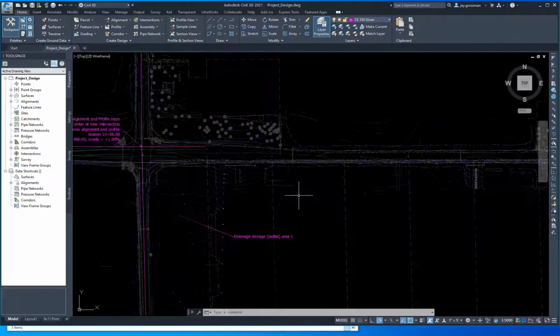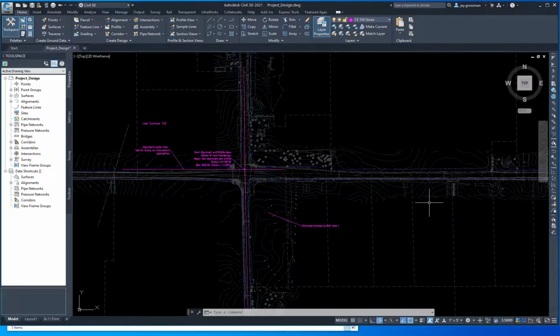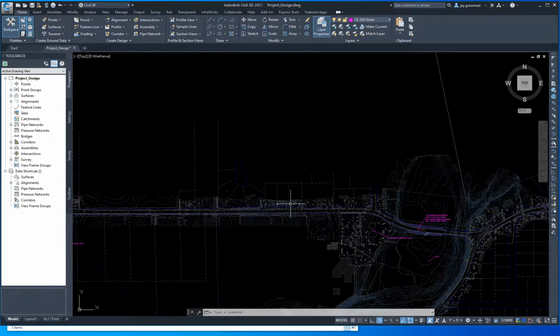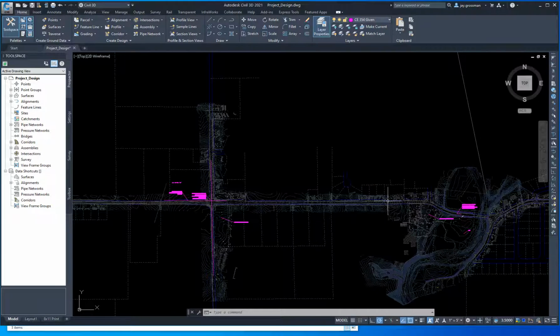You're going to look at your contours. These are your contour elevations for the natural ground level. And you're going to decide if I'm going to move the water down this direction through my ditches and then have a culvert pipe and cross over here and put my water in this area, or am I going to bring water this direction and bring it to this point. Either way, any water that falls along your road, either north or south of it or on the road itself, has to get to either this point or this point in the end. That's what we're going to be checking for on that.